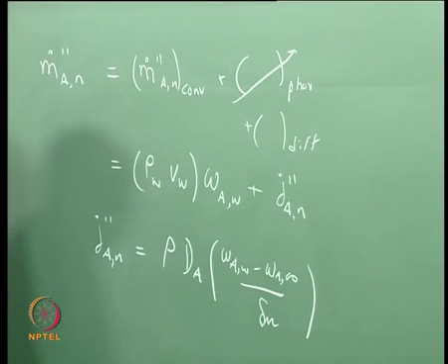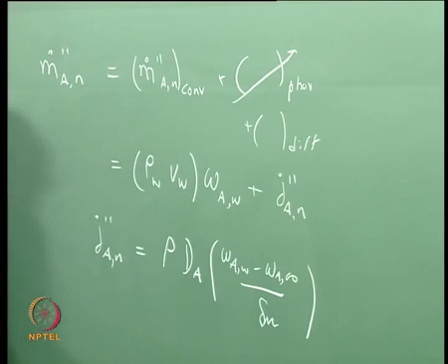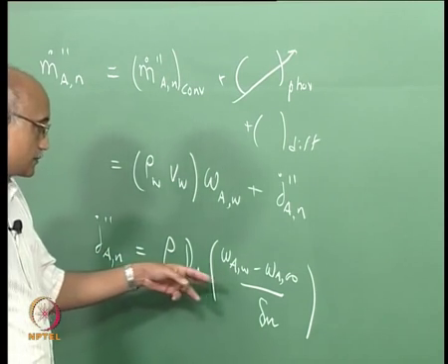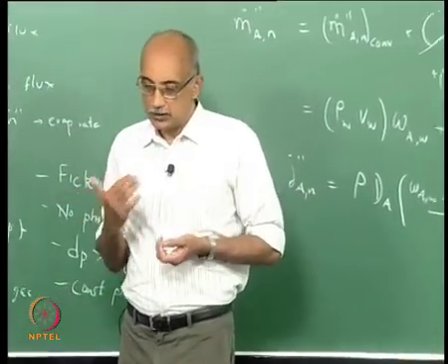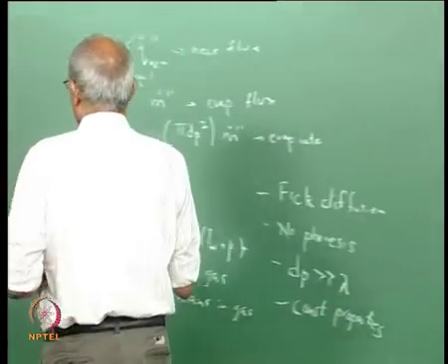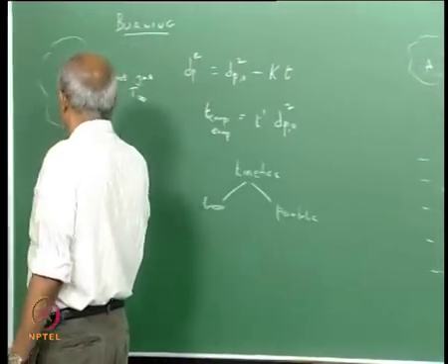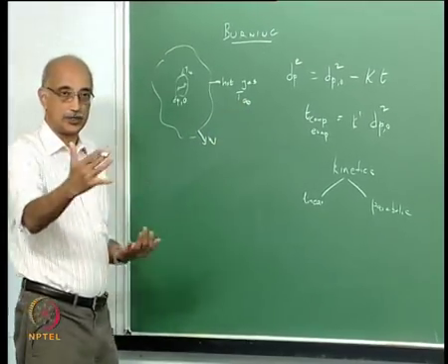a mass transfer boundary layer thickness. So, here rho is the density, D A is the Brownian diffusivity of species A in the hot gas, omega A W minus omega A infinity is the difference in mass fraction of species A from the outside of the droplet W to far away from the droplet infinity.